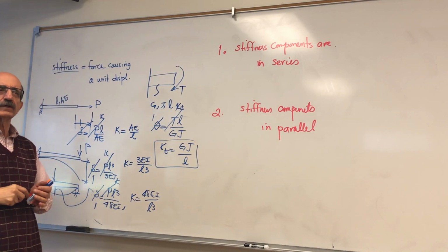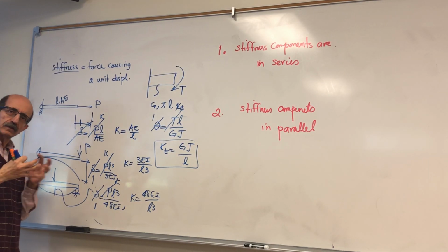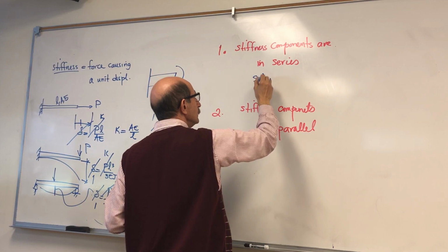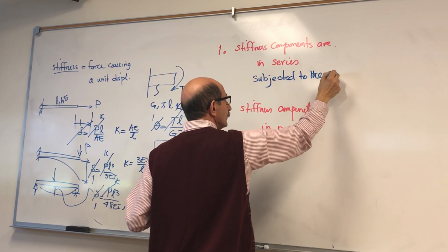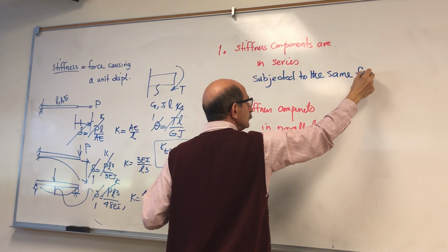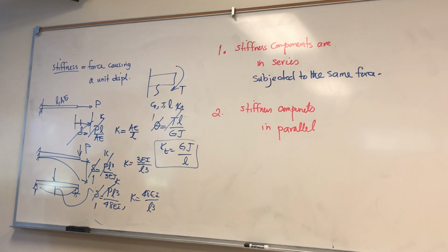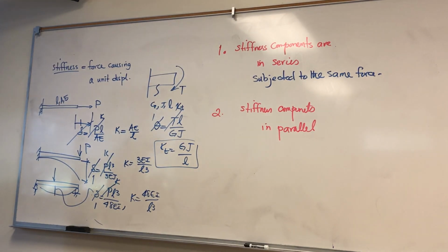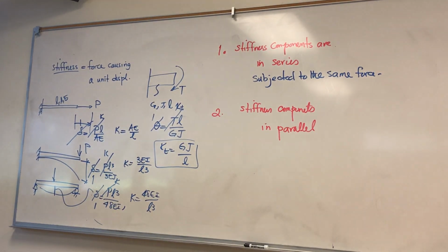There are two very important cases that we encounter. Either all the components of the structure are subjected to the same force. If they're subjected to the same force, we say they are in series. The reason for that is, as we will see, the equivalent stiffness derived for this case is analogous to the way resistors in electrical circuits are added up.